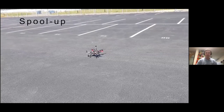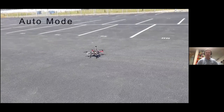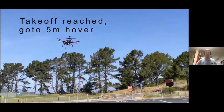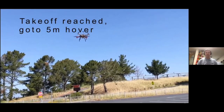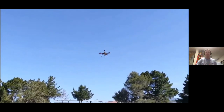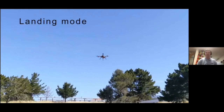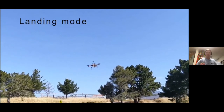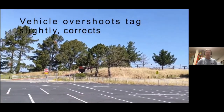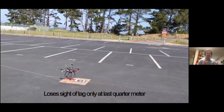Spool up is when we're getting the motors started, because unless all four are running, the vehicle will flip over. Auto mode is automatically determining the GPS coordinates to travel to and just following a pre-programmed mission. It will go to a 5-meter hover and then wait there for 3 seconds. I start moving the tag when it reaches that hover. It then enters landing mode and is now pursuing to catch up with the tag. Here, it slightly overshoots the actual location of the tag and corrects its positioning, and then continues its descent.